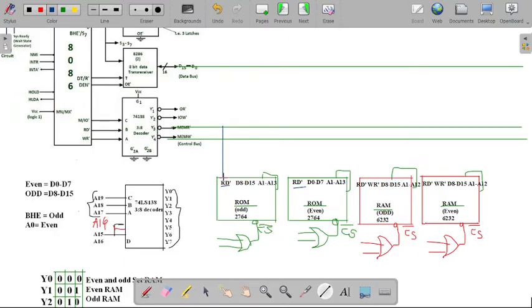So I have given this connection here. Now, whenever I am considering the RAM structure, there are 2 signals available, that is read and write signal. So here it is a read signal and here it is a write signal, that is memory read and memory write. And with the help of these two signals, we are doing memory interfacing. So I'm connecting this read signal as well as this write signal. So now we have done with that read and write signal.